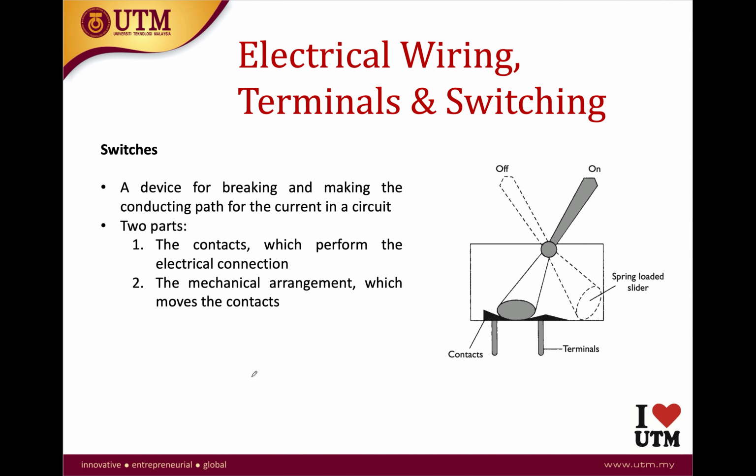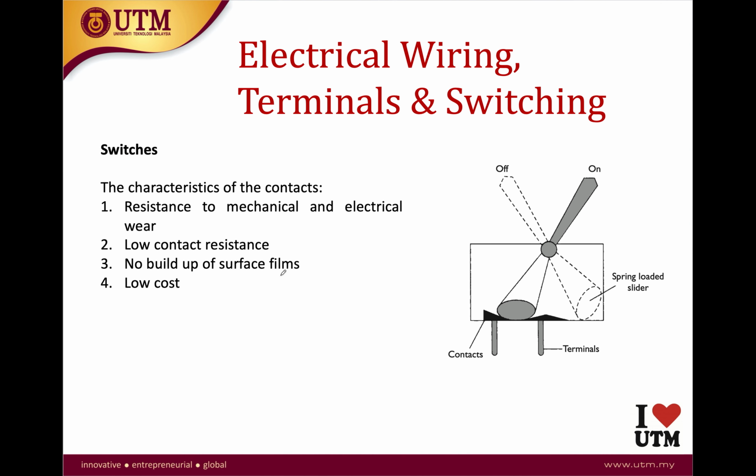Besides terminals, or terminations of wiring, you also have switches. Switches will switch on and off, basically giving you either an open or closed circuit. There are two parts to it: the contact and the mechanical arrangement which moves the contact. Switches usually have to be resistant to mechanical and electrical wear, with low contact resistance, no build-up of surface films, and low cost.